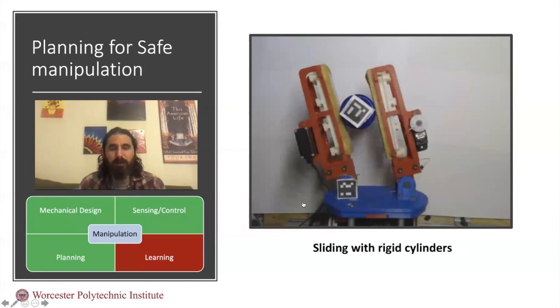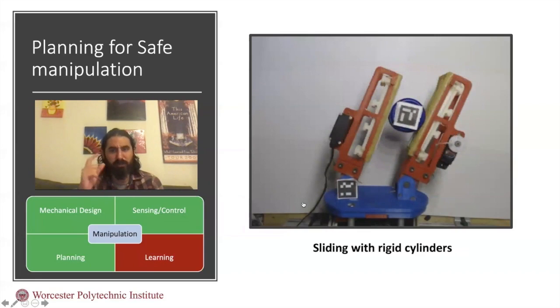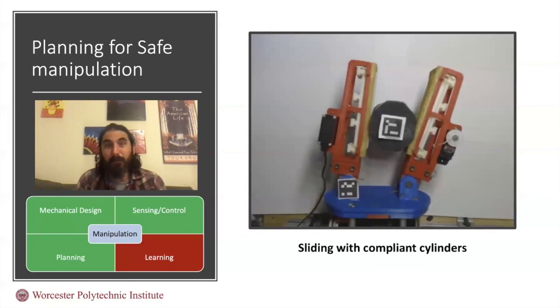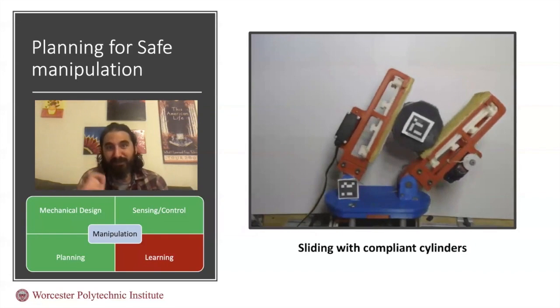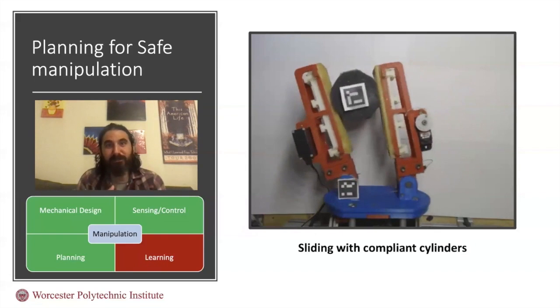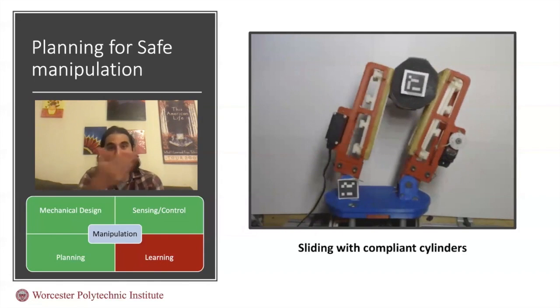We always need a flat surface in order to achieve reliable in-hand sliding. And when the object is fully round, we were not able to have reliable controlled sliding. However, with deformable objects, by squeezing the objects a little bit, we were able to create those flat surfaces ourselves. So we were able to achieve in-hand sliding in an even more reliable way than the rigid object case.